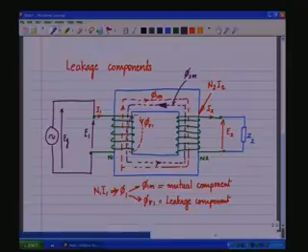But this also produces some ampere turns which push some flux through the air here, and it has a path something like that, and this is called phi sigma 2, and this is the leakage component of the flux due to N2 I2 ampere turns, and this phi sigma 2 does not link with the primary, only phi 2m links with the primary.